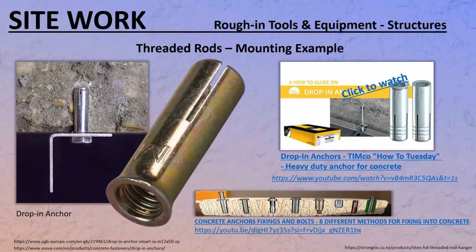And then for some of those drills, you have special attachments for those drop-in anchors. So you drill that hole and then you flip it quickly and put that attachment onto the end of the drill and drive that in. So it takes maybe a second and a half to drive that in, as opposed to hammering that for 20 seconds. And if you have a lot of them to do, then it makes a difference. These are called drop-in anchors.